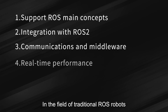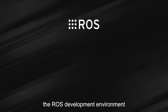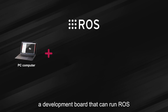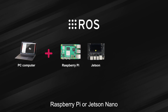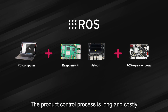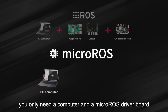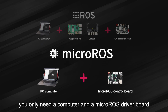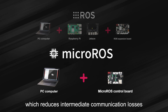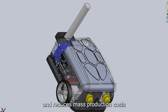In the field of traditional ROS robots, if the robot device wants to access the ROS development environment, it needs at least a computer, a development board that can run ROS, such as Raspberry Pi or Jetson Nano, and a ROS expansion board. Then, connect it to a peripheral driver board to control the robot. The product control process is long and costly, and real-time performance cannot be guaranteed. With MicroROS, you only need a computer and a MicroROS driver board, which reduces intermediate communication losses, makes the product smaller and more convenient, and reduces mass production costs.